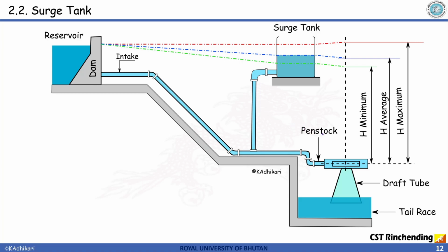Okay. So let's say there is some valve here. If we close this valve, what happens is water is flowing with tremendous velocity, like I have explained here, right? The water is flowing with tremendous velocity. So when velocity at this point is suddenly made zero, because of the momentum, there will be immense pressure rise in this section.